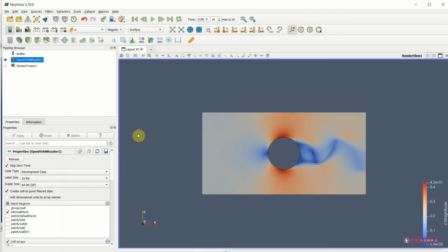You can do section cuts. It's not so interesting with this structure, but there are possibilities for section cuts. The best really is to just experiment with using ParaView to see different visualization options. I think that covers basically all I wanted to. It's a very simple, trivial problem perhaps, but it does show the principles of how you set up and perform an OpenFOAM analysis.